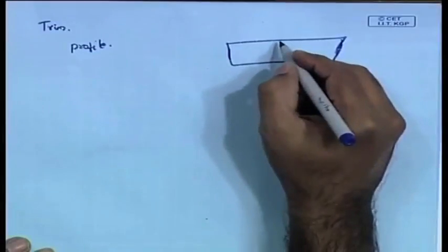We are going to follow the same principles as in the transverse direction. The only thing is the difference between the transverse direction and the longitudinal direction. Other than that, all the principles remain the same. There is a metacenter M, there is a center of buoyancy B0. It is because of the trimming, instead of heeling. Remember that we were talking about heeling in the previous section.